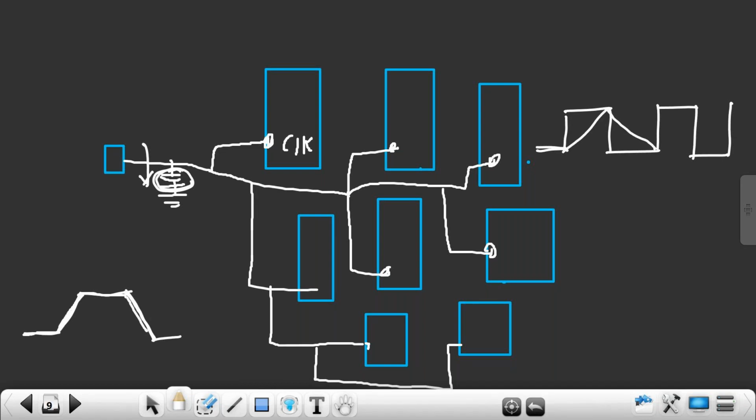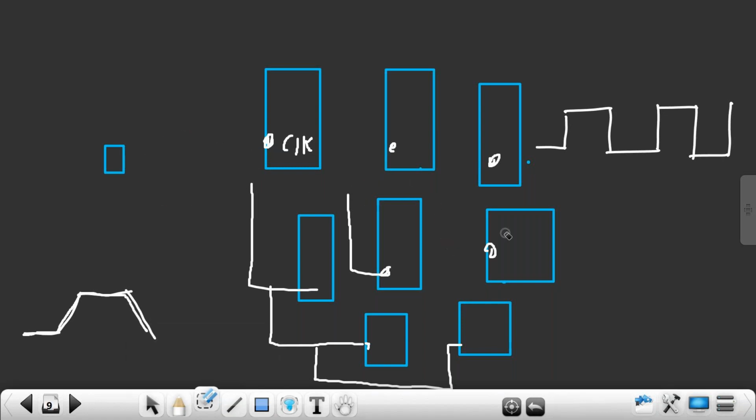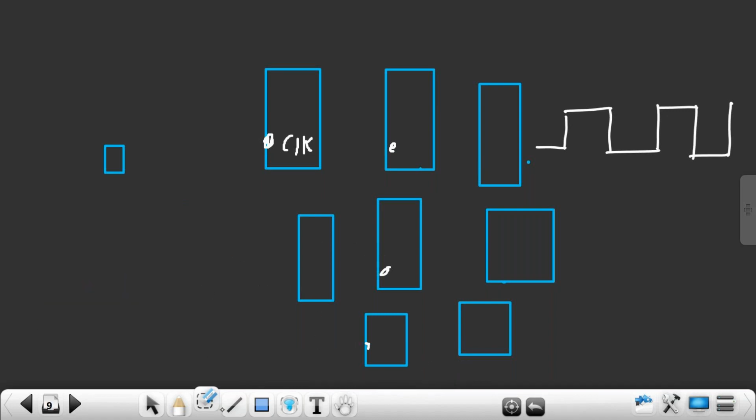So what is the intention of clock tree synthesis? It is to reduce this load. What you do is reduce the load by inserting buffers. I will start connecting through buffers and inverters. From the clock port, I use 2 buffers.